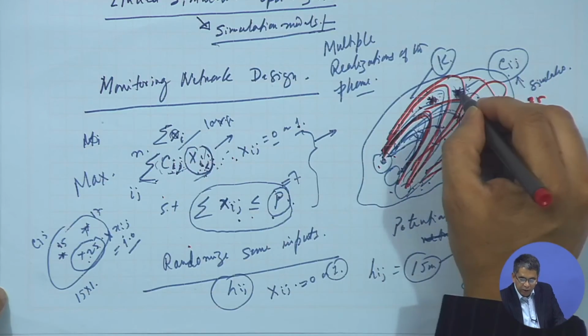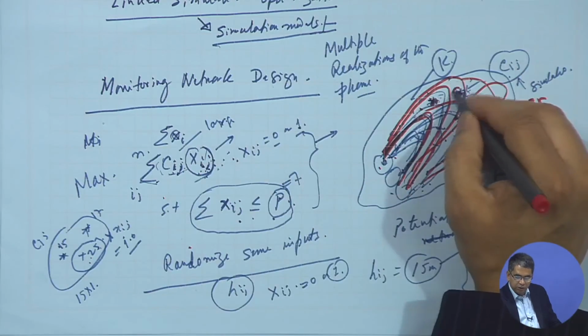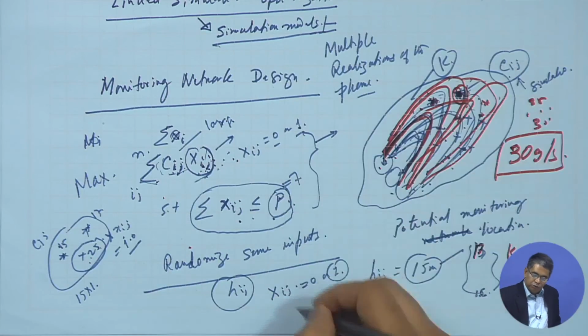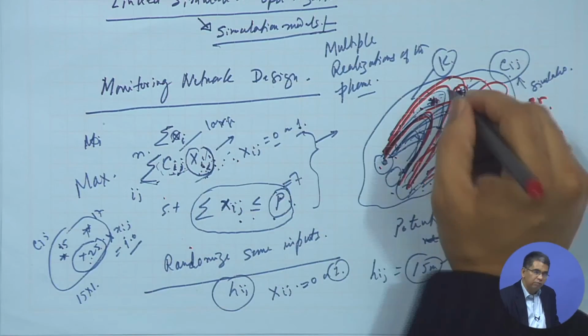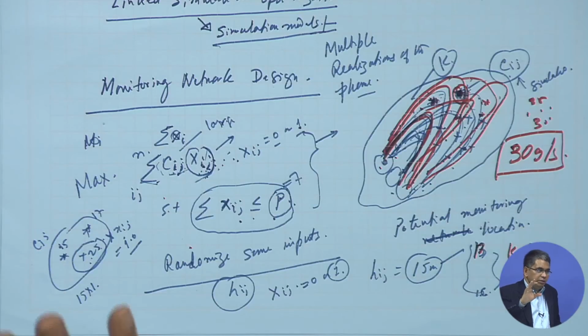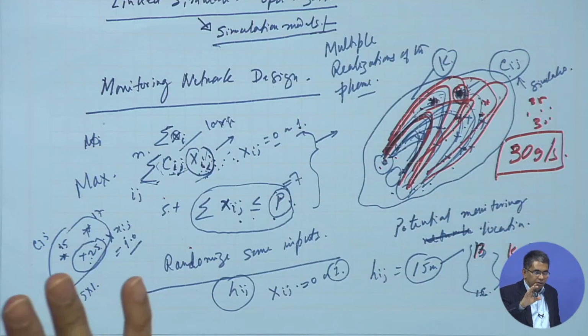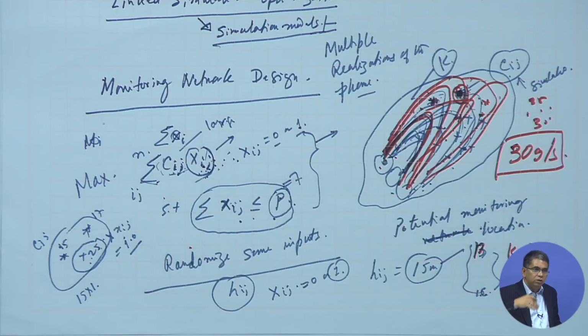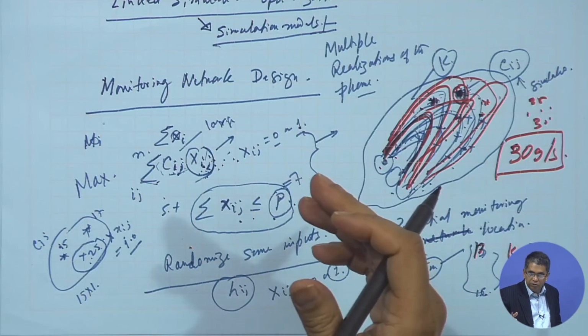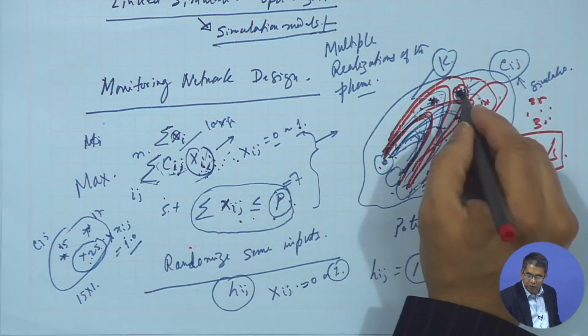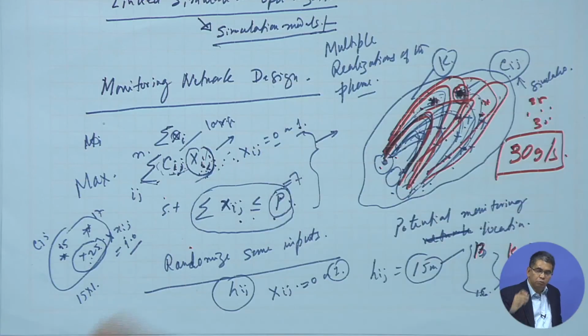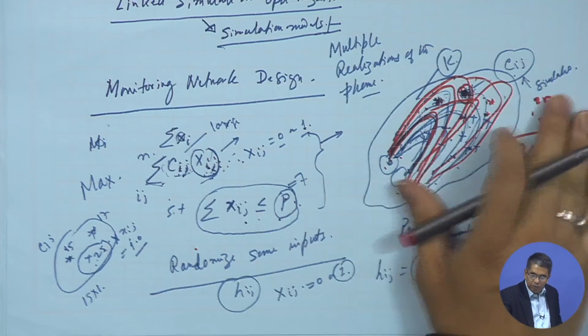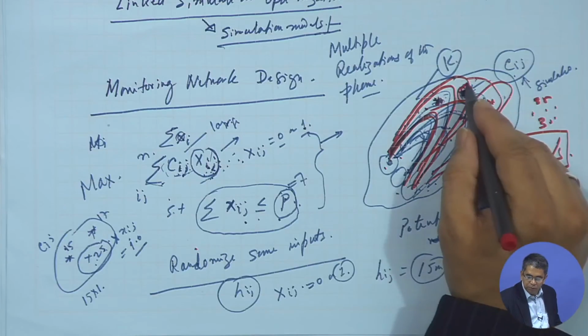So here I will not only choose one value which is coming as a concentration at this point, but I might choose the summation of the values which is coming from all the plumes which have been generated. Understand what I am saying? So I have generated maybe 20 possible plumes. So I will pick up those 20 values at that point, which is coming from 20 different realizations of the pollutant plume. How those 20 pollutant plumes are generated?